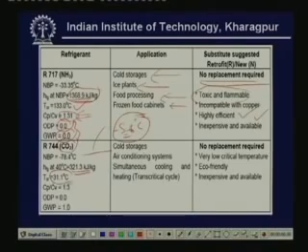Major problem with this is its critical temperature is very low. That is the reason why it was phased out. But alternate cycles have been devised, that is the transcritical cycle, where the condensation process is replaced by a gas cooling process, and this has made a strong comeback because of this reason. That means because of the modification in the cycle.